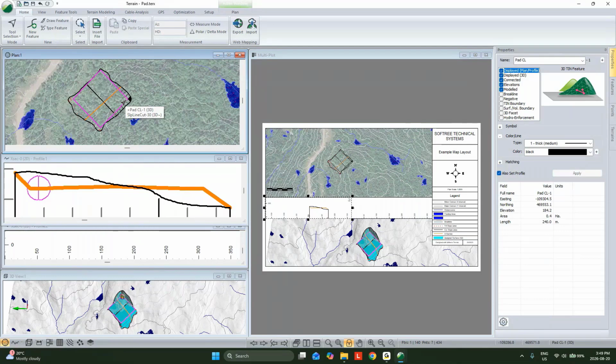If it was another case where maybe we wanted to have the ditch run on an independent grade, separate from whatever slope the pad's set on, we could do that too. We just define that tabularly and pick our highest point, typically, and we'd run that around the outside of the pad.